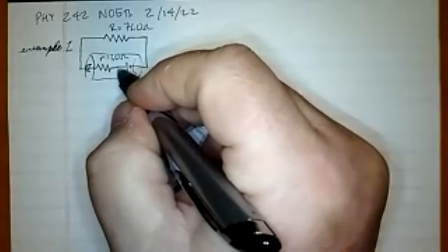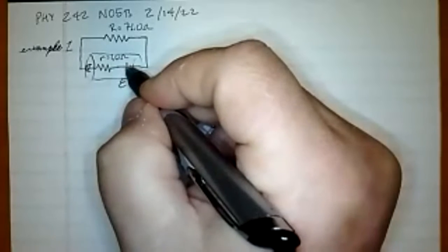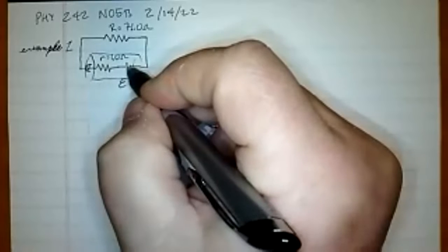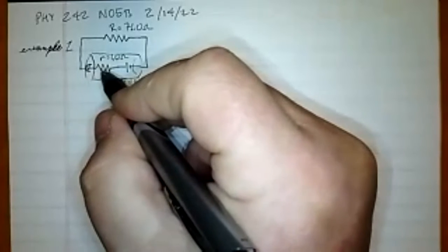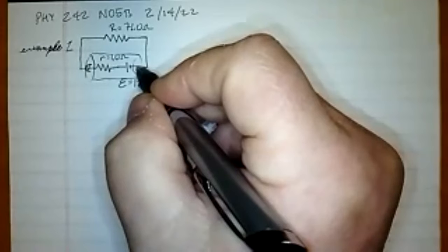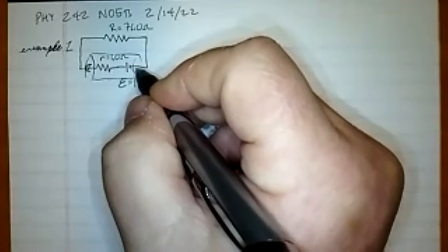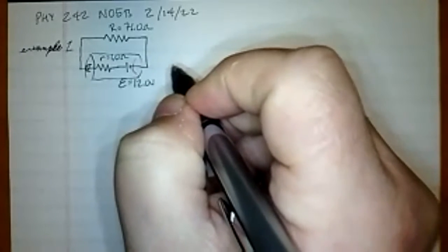And that current multiplied by 1 ohm tells you how much the voltage drops. So it'll go from 12 to 12 minus I times R at this point. So that would be the terminal voltage. Well, actually, technically, the terminal voltage would be 12 minus I times R minus 0, because there's no given rule that says the bottom of one battery has to be 0. That'll make more sense when you start to see multiple batteries in a circuit, and you'll be like, well, where's the 0 voltage? Well, you don't know. Sometimes you have to work that out.